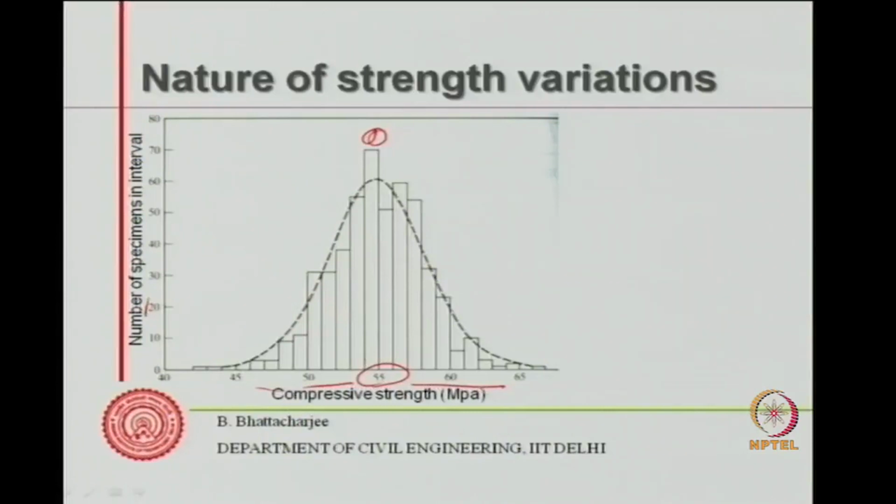For example, it would depend upon the error in mixing, proportioning. First of all, what we call batching. There would be some kind of error in batching. You wanted to put 180 liters of water, but your measurement system might have put it around 180 instead of 185, or 190 instead of 185.